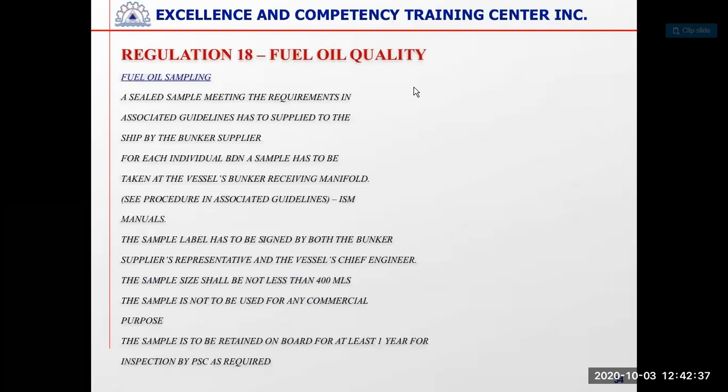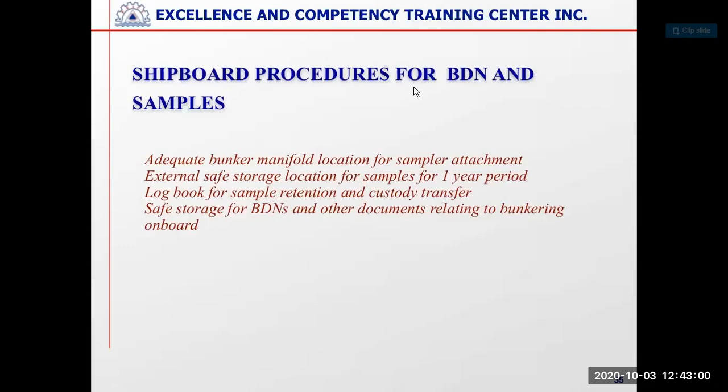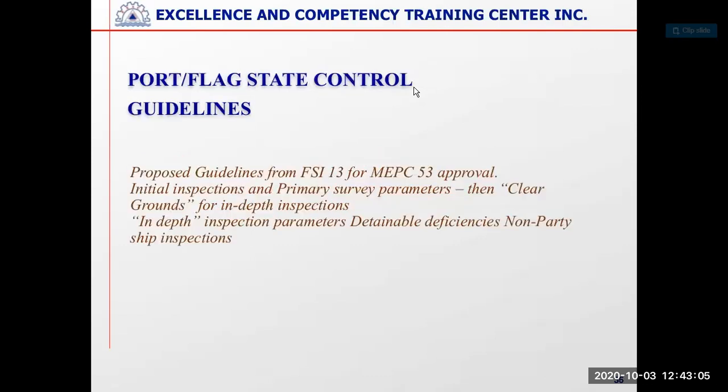Then these are the fuel sampling requirements. Sealed sampling is required as per the guidelines, and the BDN has to be there. Then you need to put a proper label: where the sample was taken, bunkering done, size of sample is 400 ml, and the sample has to be retained for at least 1 year. And port state and others have to do the inspections.